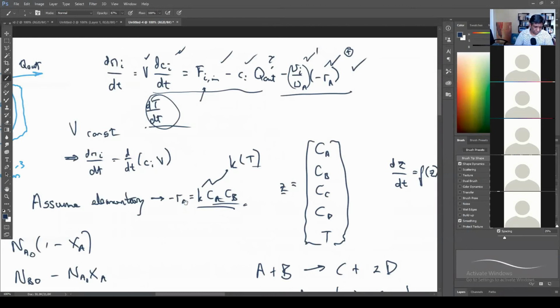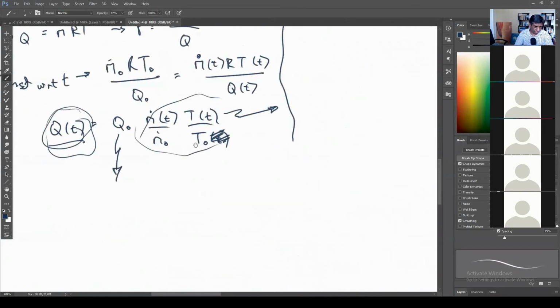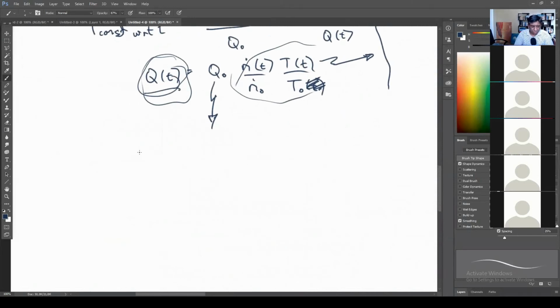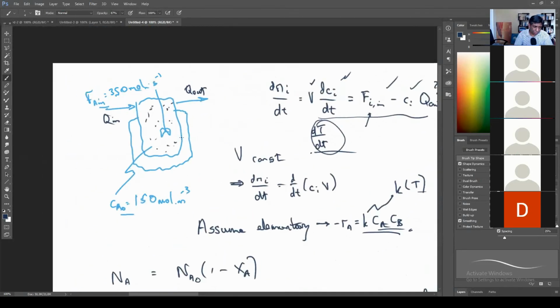So to estimate Q, a little bit of notation collision here. Let's call it small q for the heat transfer rate. So let this be heat transfer rate. So small q is UA (T minus TA). Right, so be careful that you get the right delta T in there, because of course the heat being transferred is between these two things.